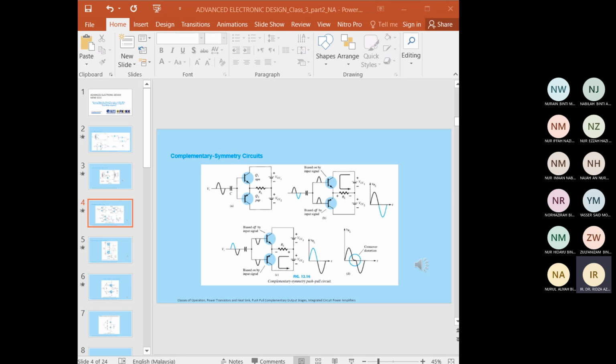And then during the negative half cycle of the signal, the PNP transistor Q2 will conduct, and the negative half will be generated that you can see in this figure C. For the first positive half, only the NPN conducts, while the PNP Q2 does not conduct. So the result is the positive half cycle, but at the negative cycle it is the opposite. The NPN Q1 will not conduct, but the PNP transistor Q2 conducts, and the output results in the negative half cycle.